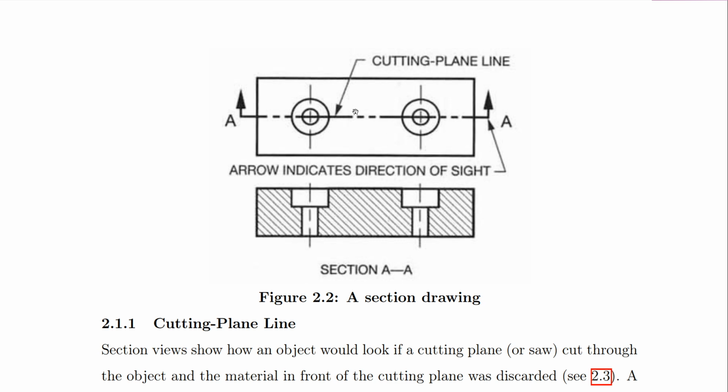If we are to draw the front view of this in the orthographic projection, we are going to have the outline of these features presented in short dashes, to indicate that these features are there. But the moment we section through it, we have revealed the features. So we use continuous thick line to indicate the outline of the features inside.